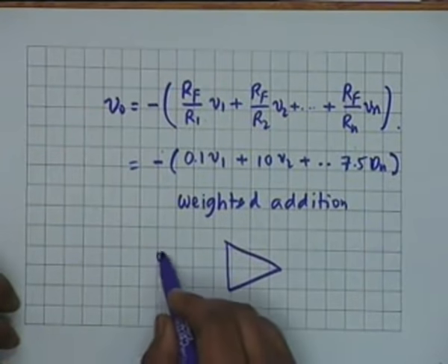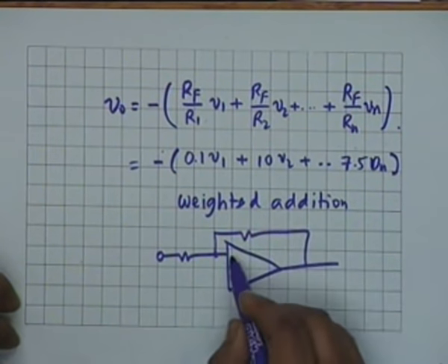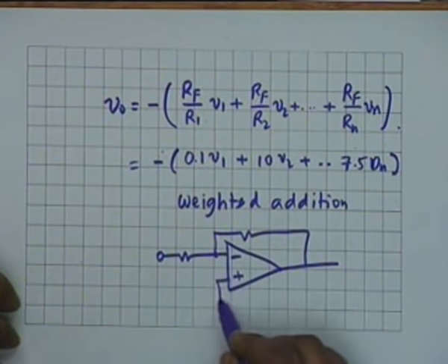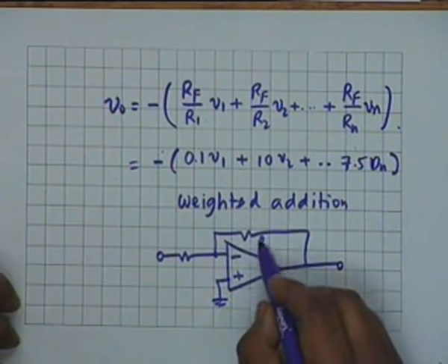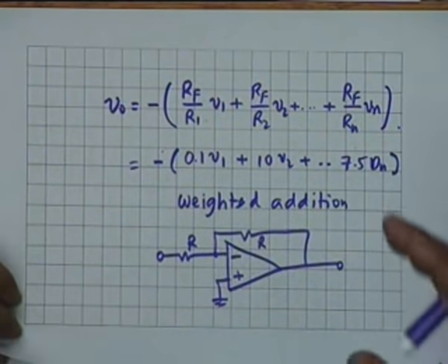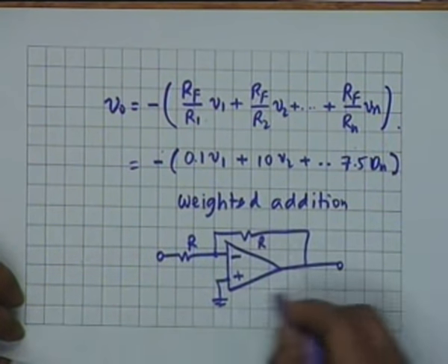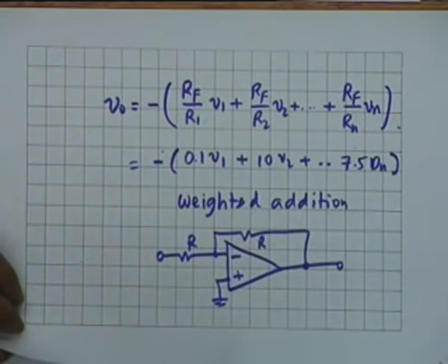You take an op amp with a -1 gain, which is simply this op amp, minus, plus, this is grounded, and this resistance is the same as this. So all I do is I connect in cascade another stage like this, and then this is simply a sign inverting stage, that means a stage with a gain of -1.